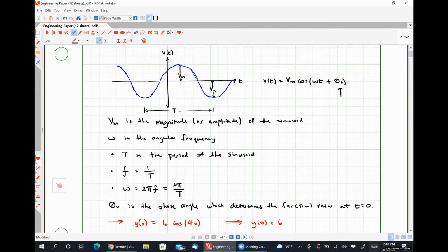in the horizontal direction. So if we slide it to the right, we're having negative phase angles. If we're sliding it to the left, we're introducing positive phase angles. That may seem counterintuitive, but it's all about the way that we read the graph, okay? And so what I mean by that is if the origin is t equals 0, then all of the points to the right are later in time than t equals 0. And so we need to introduce a delay to get there, which is where a negative phase angle comes